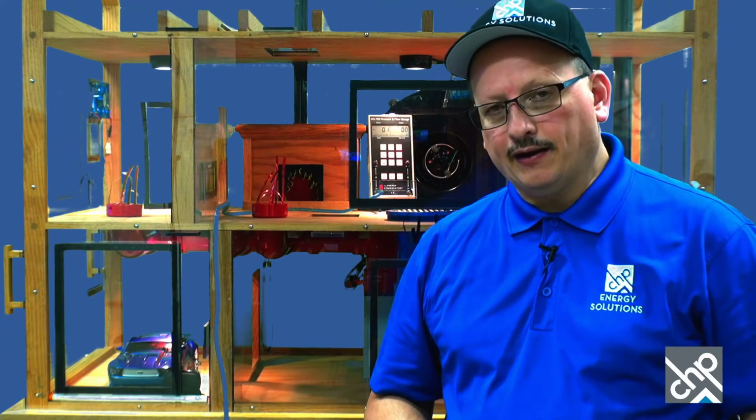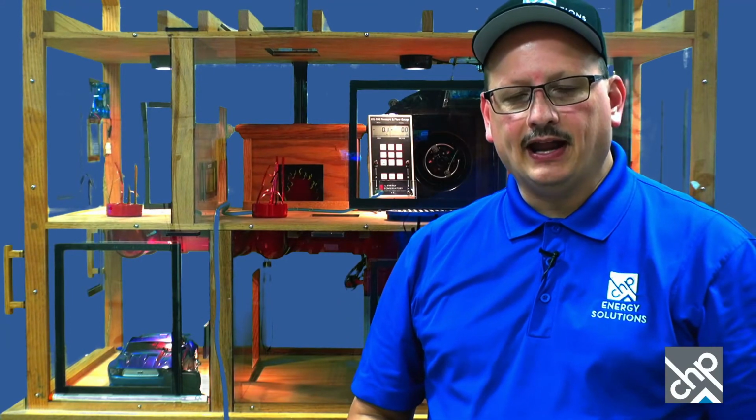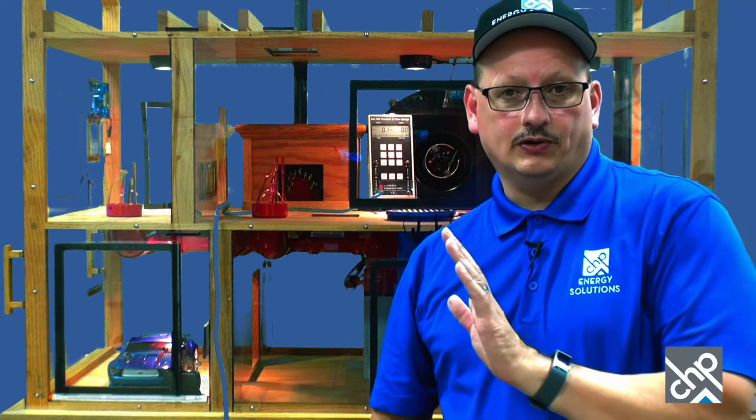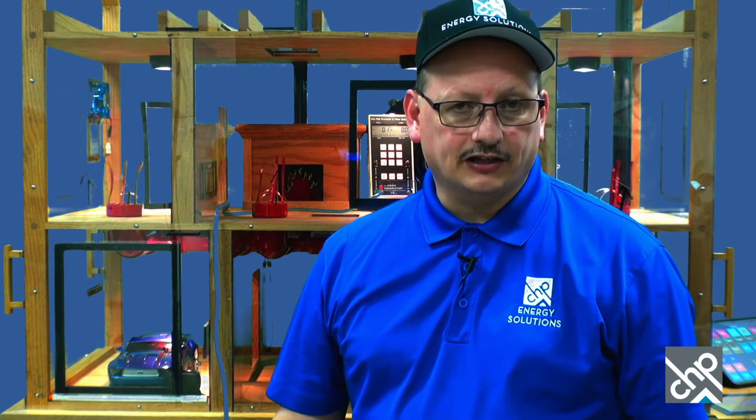You've got what's called an alcove. You've got a unit in a little hallway kind of closet, which may or may not have a door on it, but even if it has a door, it should have a louver that pulls air from the hallway. But the thing about those, same deal, on the mobile homes you have supply air that blows into the bedrooms, but then it's got to get underneath the door, back to the house. You can also have, obviously, duct leakage on mobile homes or manufactured housing. A lot of times you don't have a return duct in those cases. The return is just at the unit. So pretty much all your leakage in a lot of those cases is going to be supply leaks, especially where the unit might connect to the ductwork.